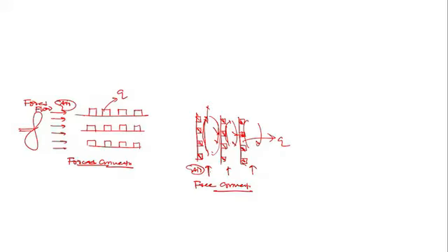Any air that makes contact with the components experiences an increase in temperature, and that increase in temperature causes a reduction in density, and since it is now lighter than the surrounding air, a buoyancy force is induced, because there are two different densities. That difference in density induces a buoyancy force, and the buoyancy force induces a vertical motion in which the warm air ascending from the boards is replaced by an inflow of cooler ambient air.